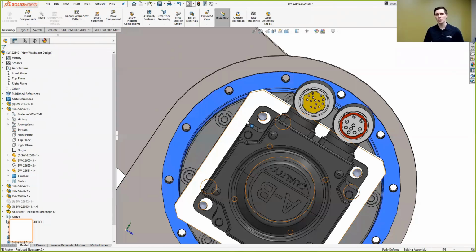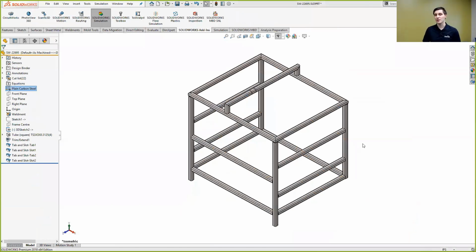We know this is still going to bolt up nicely because those bolt holes line up. We just have a bit of slop so that we can adjust the placement of this as we need for setting this up. So it's a great example where those misaligned concentric mates are really useful. And those are all controllable at the system level as well if you don't want them.